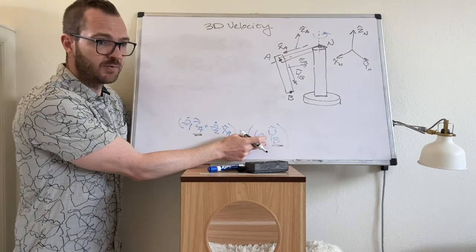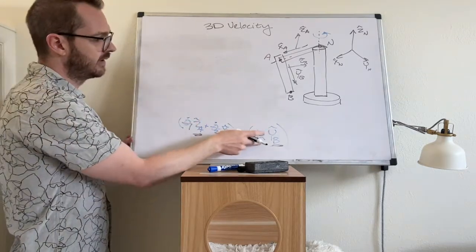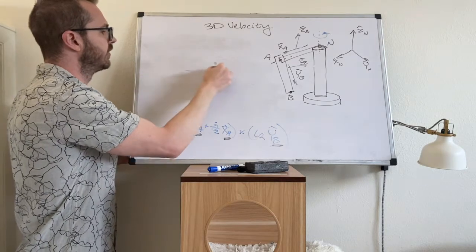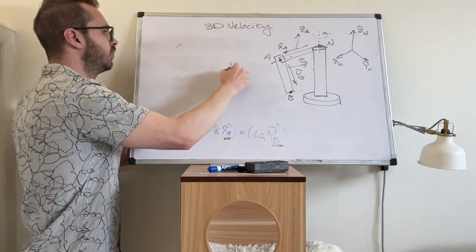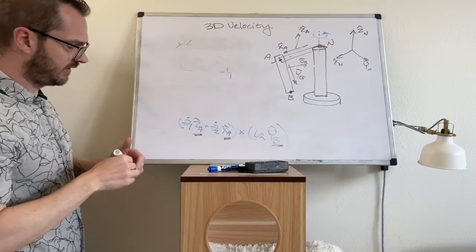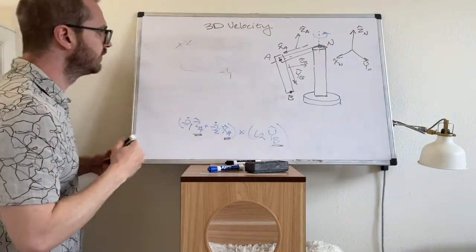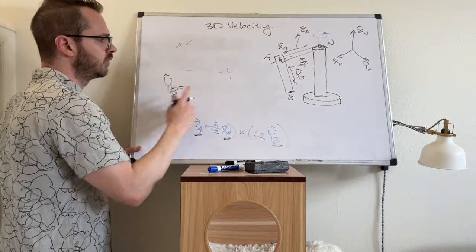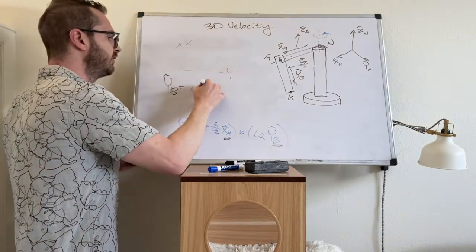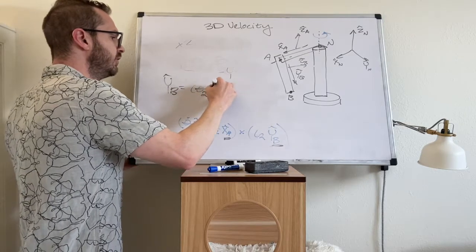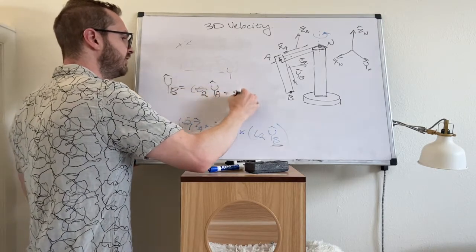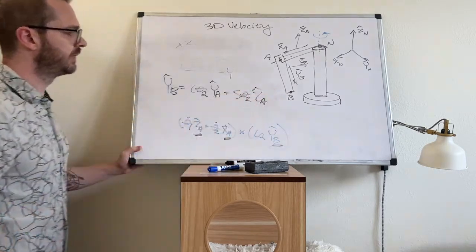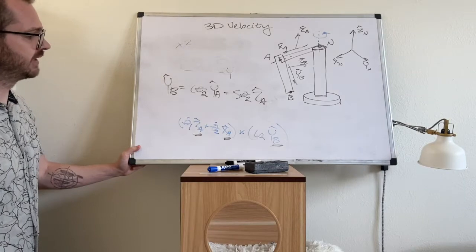Remember, on the second rotation, it was rotating about shared X. When you rotate about shared X, it's Y and Z like that. So we had written down earlier that YB was equal to cosine theta 2 YA plus sine theta 2 ZA. That was the definition of the rotation that we came up with.